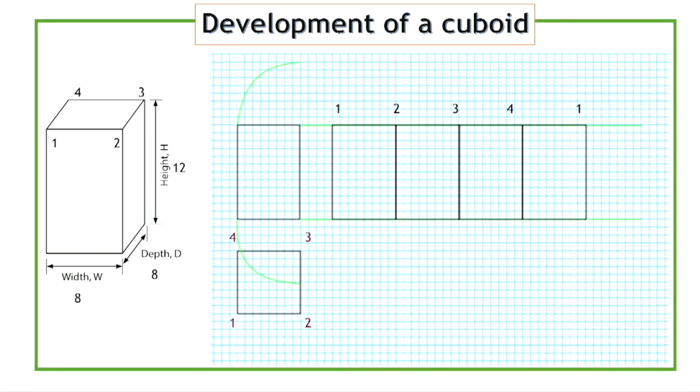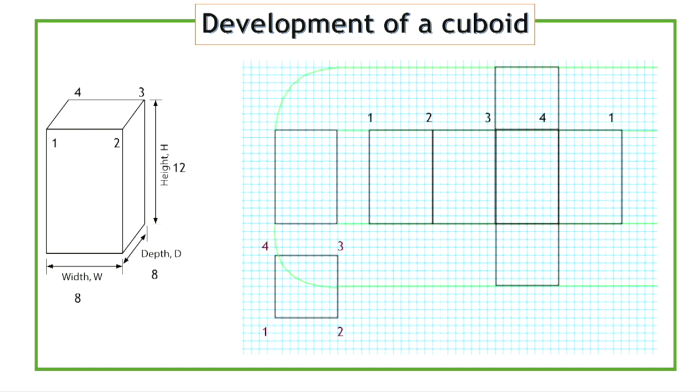To add the top and bottom faces, we use compasses to mark off the width of the top and bottom face. The width of the front is projected off to the width of the top and the base. The top and base are then completed as shown above.